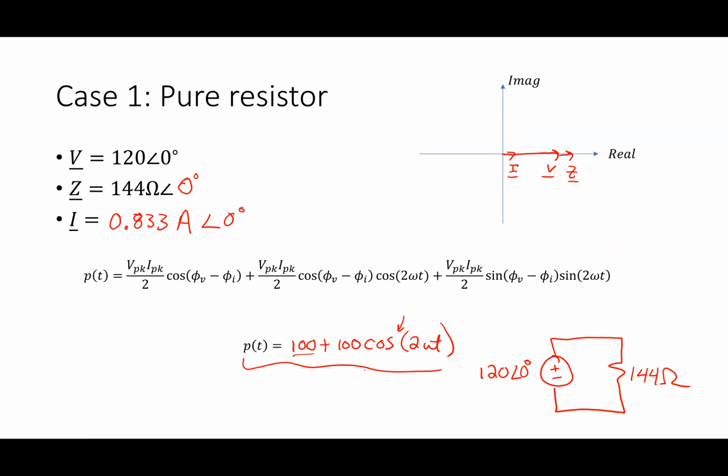What I'm doing is I'm transferring energy from a source. And what am I doing? What is this thing? This resistor. What is it physically? It's a heater, right? If I stood near it and it was cold outside, I'd feel warm, right? That's what this thing is, basically a heater. You go into a heat pump. Heat pumps sometimes have backup power called heat strips. They're just basically big resistors and there's air blowing over them, okay? So it's a heater. All it's doing is making heat.